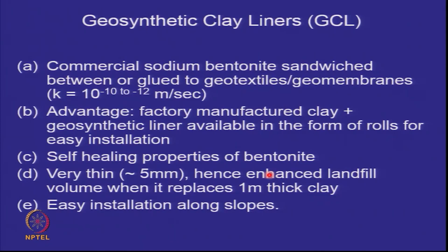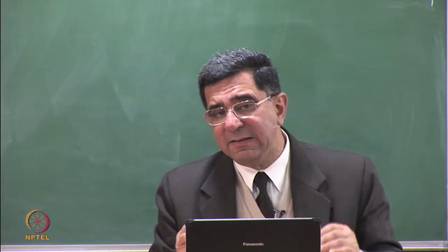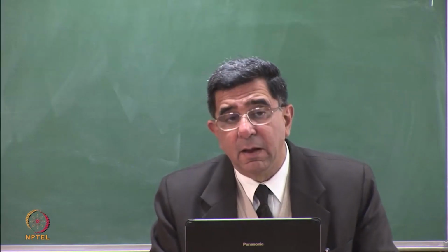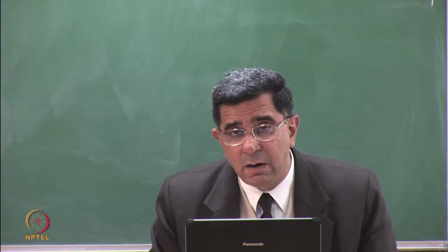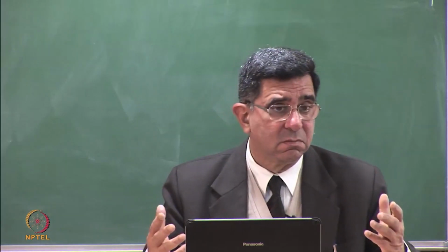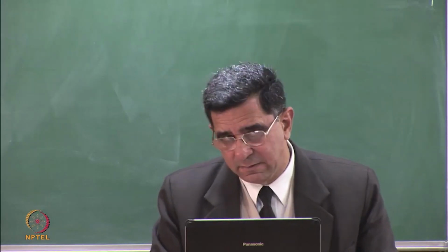The last material that I'd like to talk to you about is geosynthetic clay liners. Now, why is it that geomembranes, which are almost impervious, are not good as standalone material? Because they can have tears and punctures. What if they were self-healing?